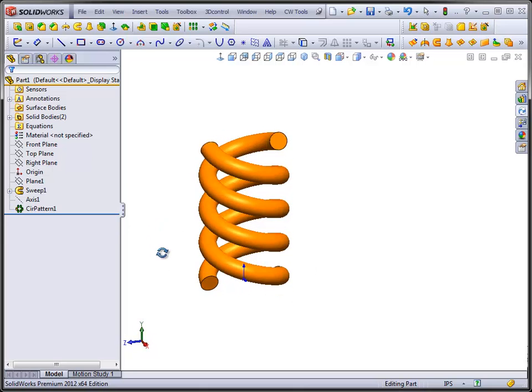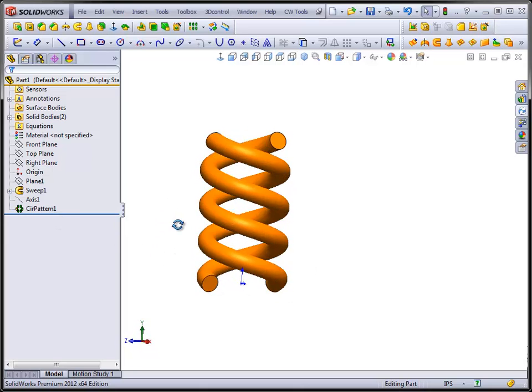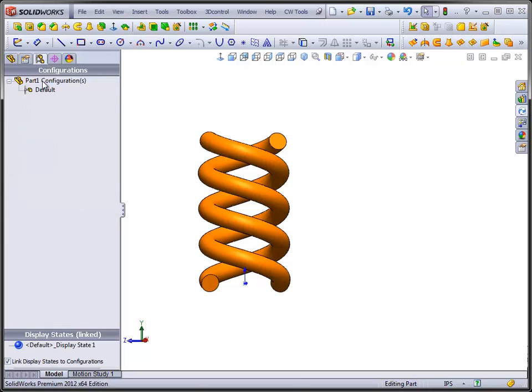Here I have a helix and a circular pattern feature, and I have no configurations or design tables at the moment. You tell me that you're comfortable with creating automatic design tables, wherein you build two or more configurations manually on your own, and you create the design table, it auto creates, identifies the disparate parameters between the two configurations and populates them as design table column headers.